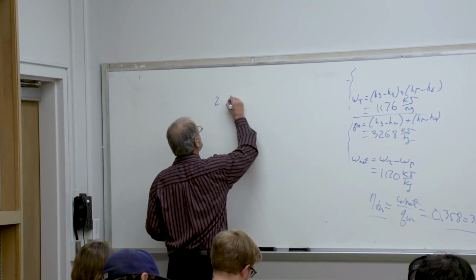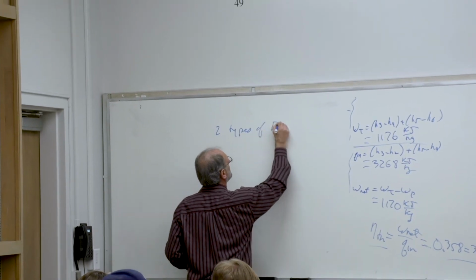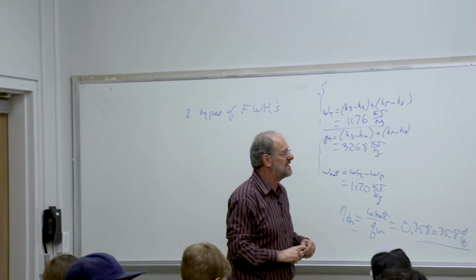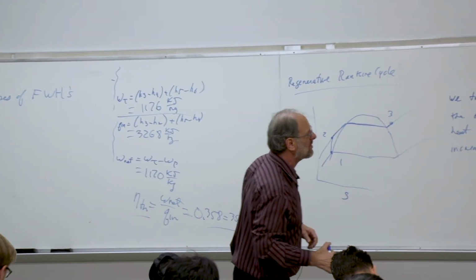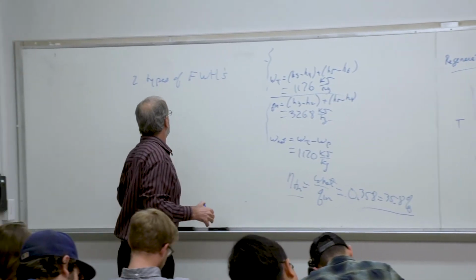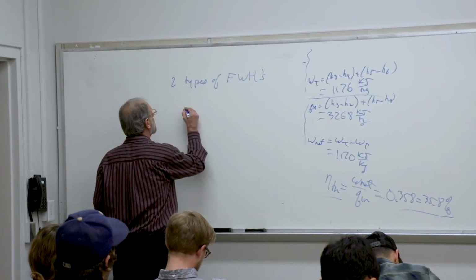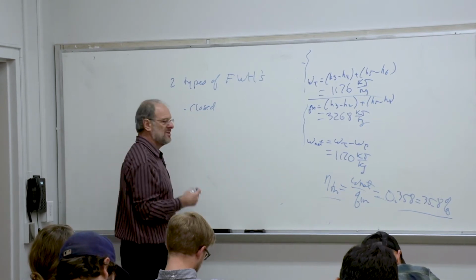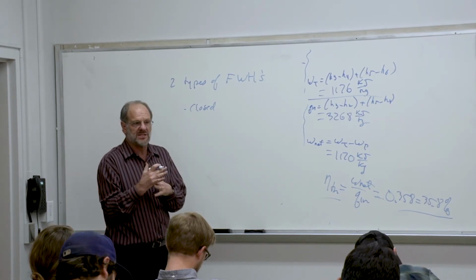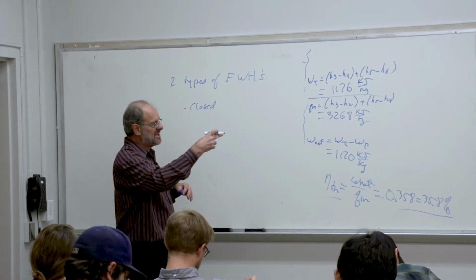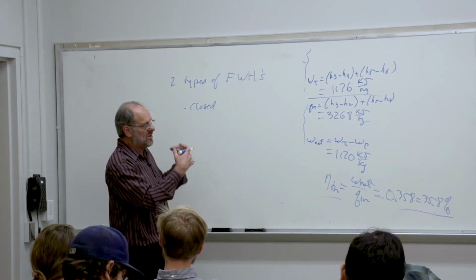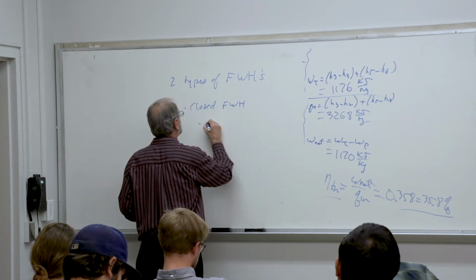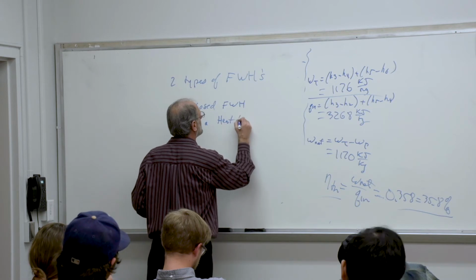So basically there's two types of feedwater heaters. And I'm just going to abbreviate feedwater heater as FWH, so I don't have to keep writing it over and over. One is called a closed feedwater heater. In a closed feedwater heater, we do not have any mixing. We take that steam and run it through a separate heat exchanger with the water. So the closed feedwater heater is actually a heat exchanger